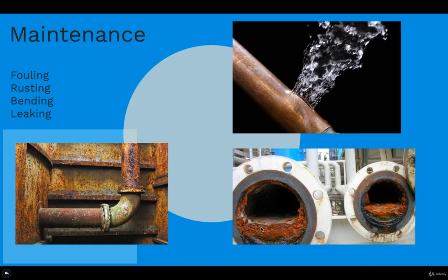One important part right here is that they will foul depending on the material. Let's say they are very viscous, high density materials. If you do not apply heat, or maybe if you decrease the temperature, they will start to clog the tube or pipeline. As you can see, if these were solid, then you have decreased almost by half the flow rate, and the cross-sectional area decreases by half, therefore the velocity will increase drastically.